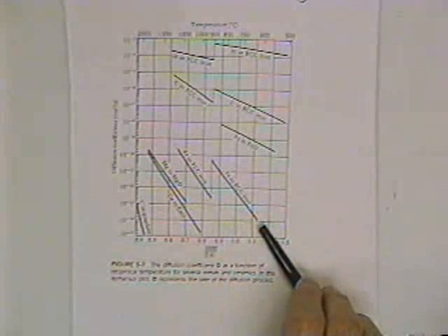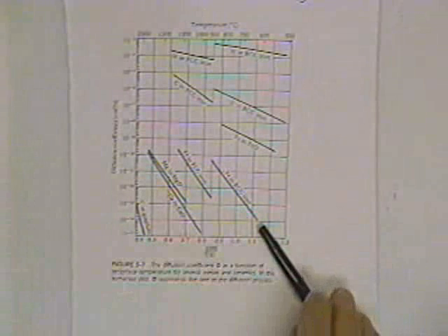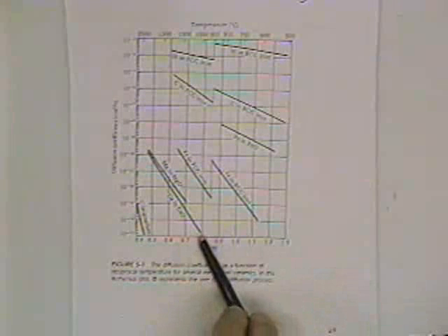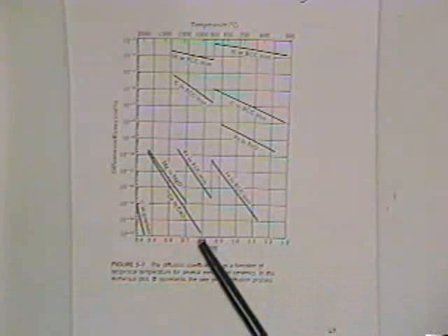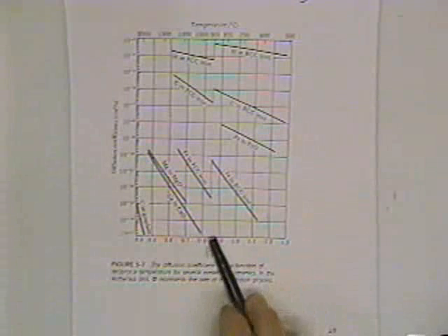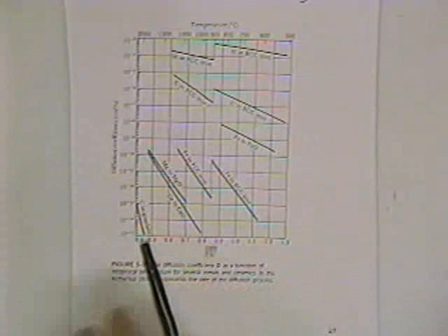For iron in itself, this is substitutional diffusion or vacancy diffusion, and you'll see that the slope is much greater, and that's because we now need, in addition to the energy to jump, we have to form a mole of vacancies. And if we go over here to calcium in calcium oxide, this is an ionically bonded material. Now you've got charges to be concerned with, and the activation energy is going to be even higher. And carbon in graphite has a very high activation energy.